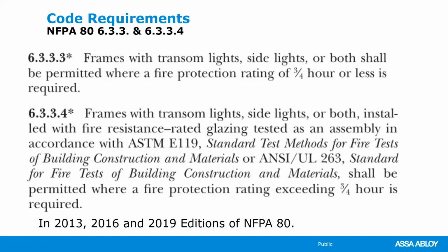So when I was looking through this and first starting, I decided to take a look at NFPA 80, which is kind of our Bible for fire rating and fire rated installation, to see if NFPA 80 called out ASTM E119 or UL 263.